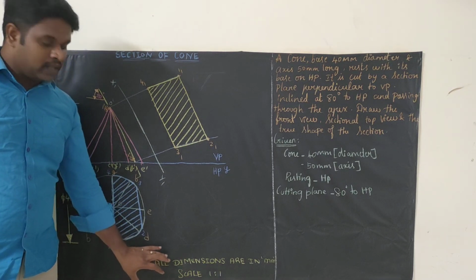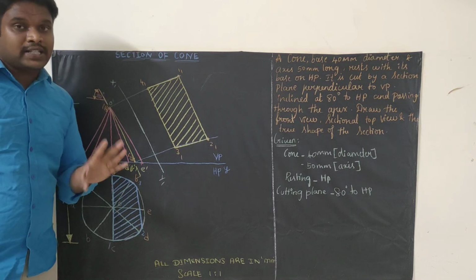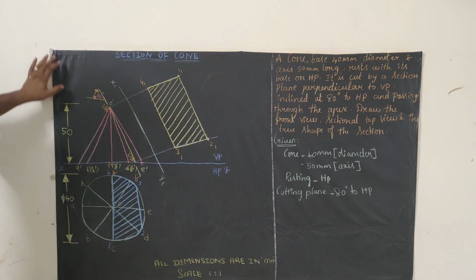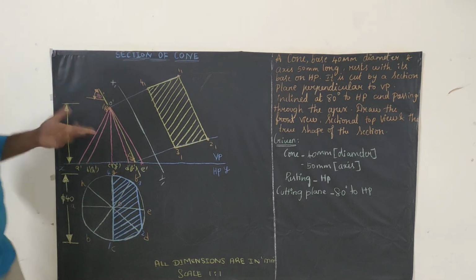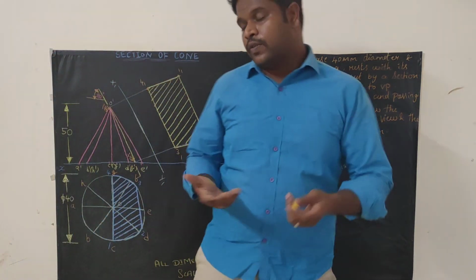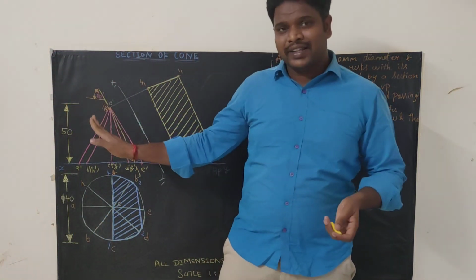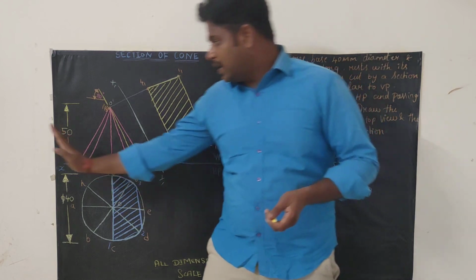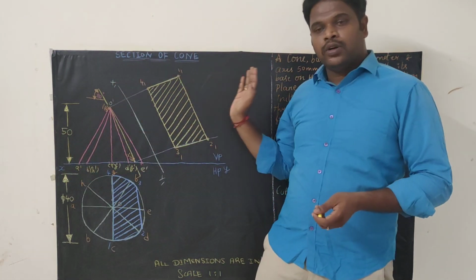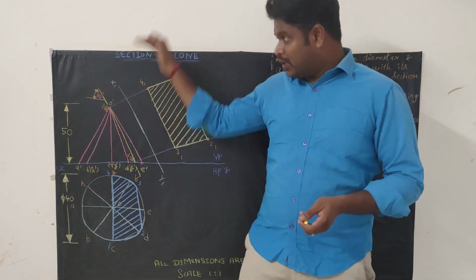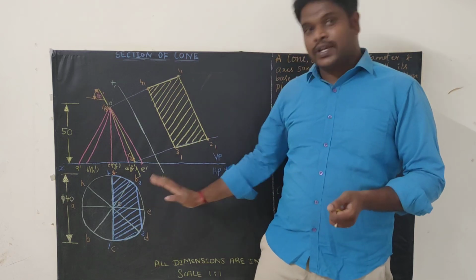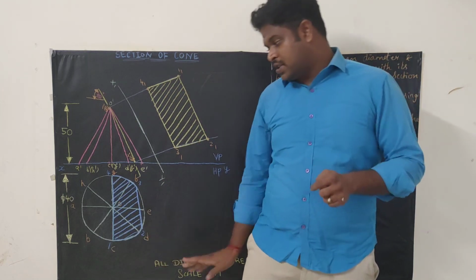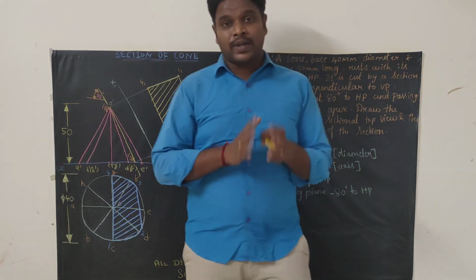These 2 lines should be written with your HB pencil, and the height of the text is 5 mm for both the lines. And here you can use a pro circle and write the question number as whatever question they are asking. And regarding the border, you have to use your HB pencil, from left 20 mm, top 20 mm, right side 10. Sorry, left 20, top 10. Right side 10, bottom side 10, all are in mm. Okay, all the dimensions are in mm. This is the way you need to present the diagram.